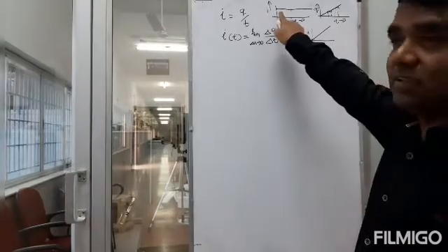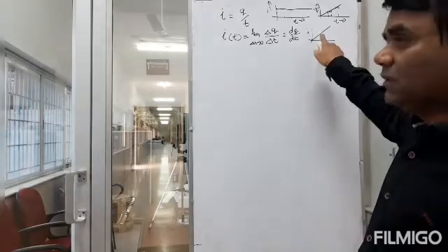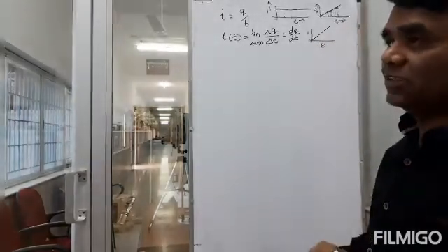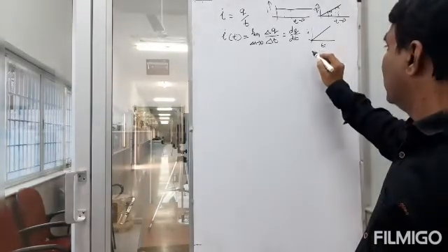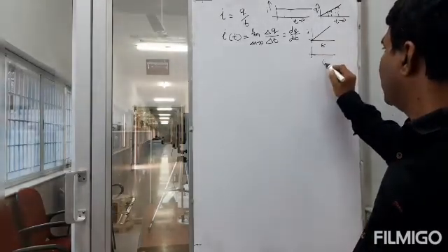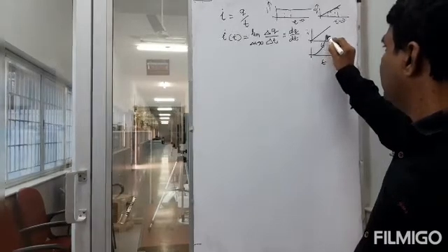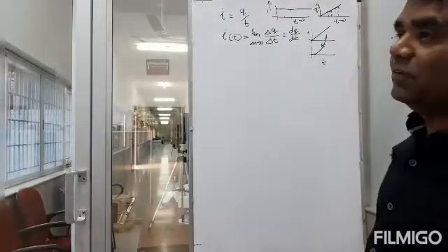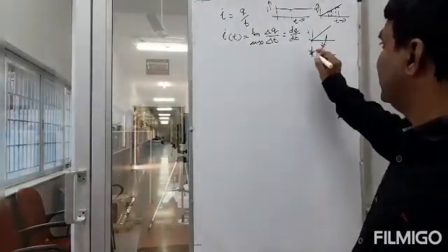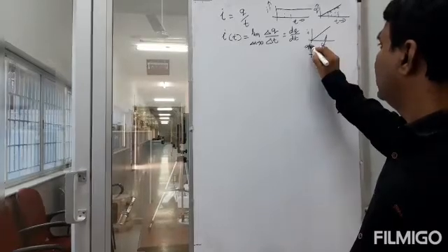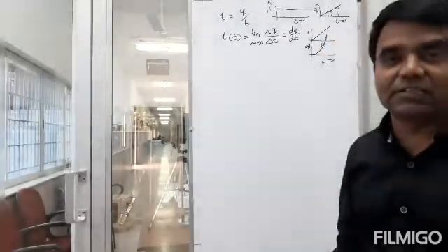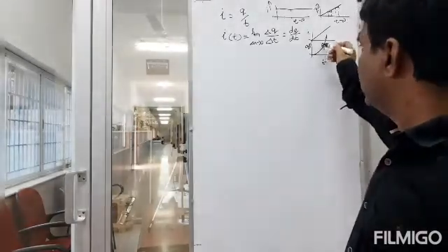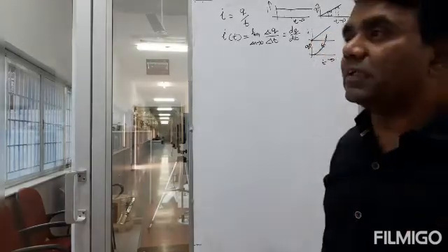You see, here you have constant current. Here you have a variable current. With time, the current itself is changing, and clearly the charge will be changing with time like a parabola. Okay, so then when you do dq by dt of that, you are going to have a straight line kind of a current with a slope. So the slope of this curve will give you the current at any point in time.